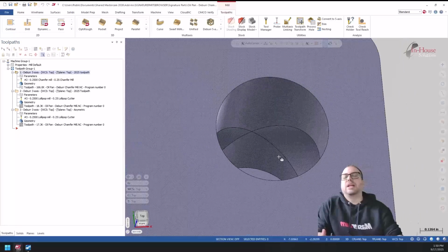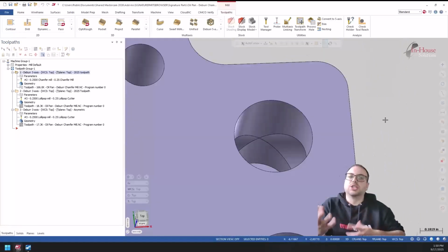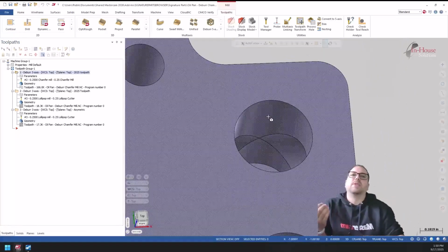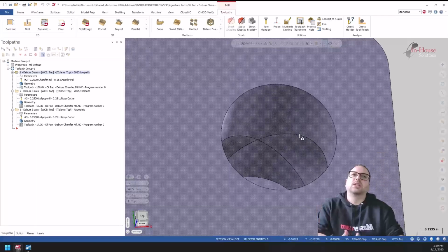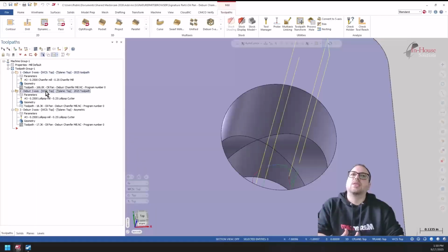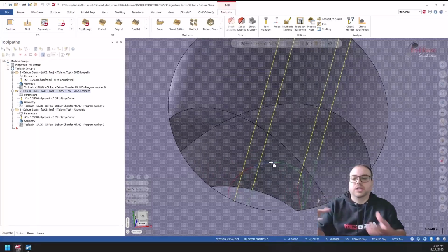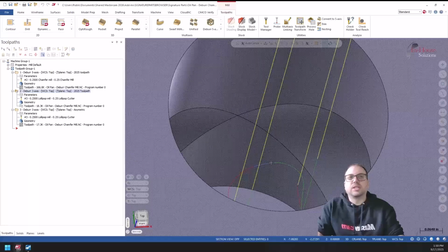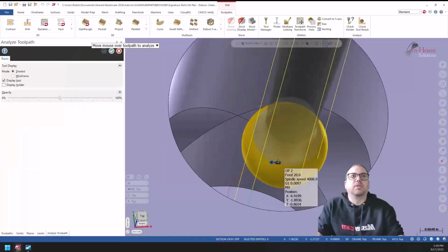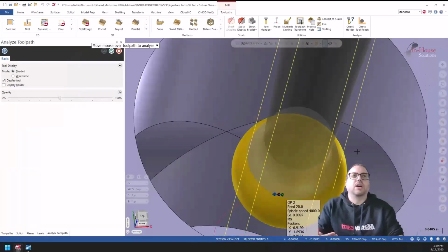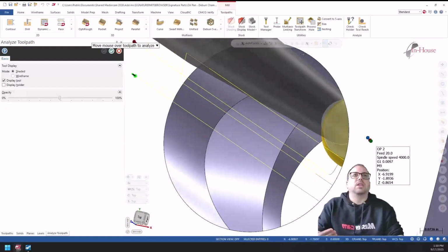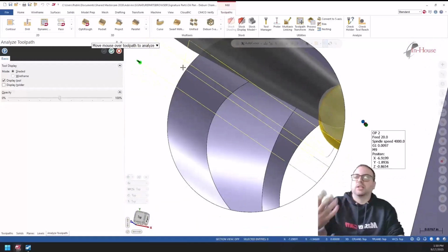Depending on your tool dimensions and also your hole size, it was actually really hard to get the toolpath to deburr those. And the reason is because of your geometry relation, it was not capable of continuing the motion without getting within the tolerance of collision and so on.